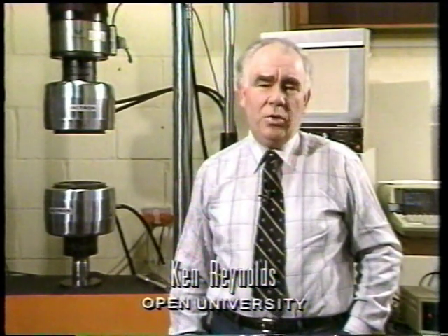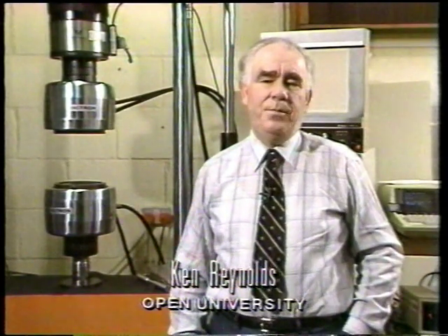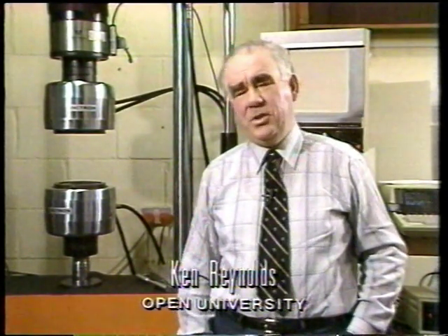In the first part of this video, we're going to have a look at two important tests for measuring the properties of materials: the tensile test and the impact test. The tensile test is important because by applying a simple uniaxial force, we can measure a range of properties which can be used directly in design and manufacture, like the elastic modulus, the yield stress, the tensile strength or fracture stress, and for manufacturing, properties which reflect the ductility, like the elongation and reduction of area.